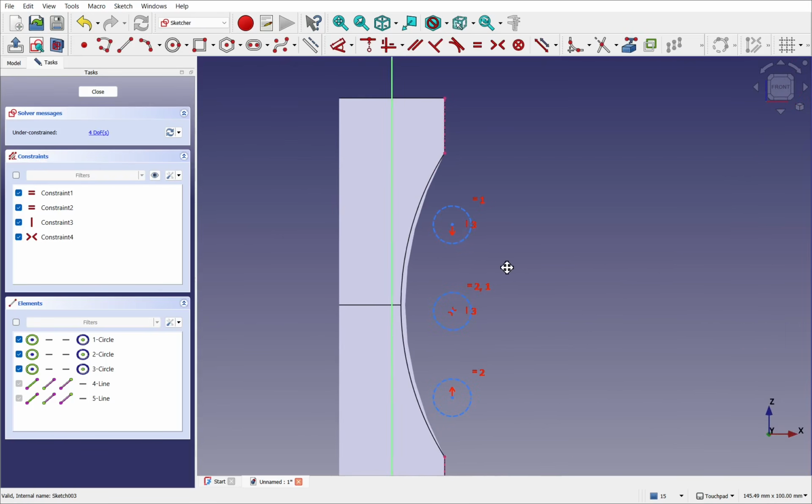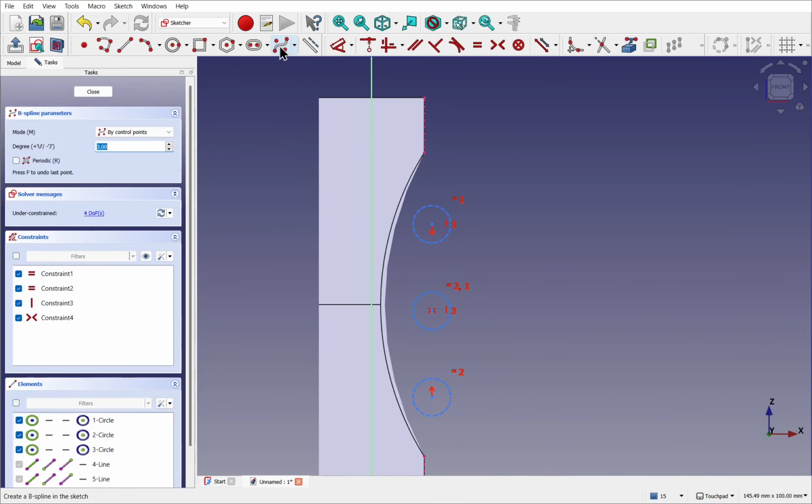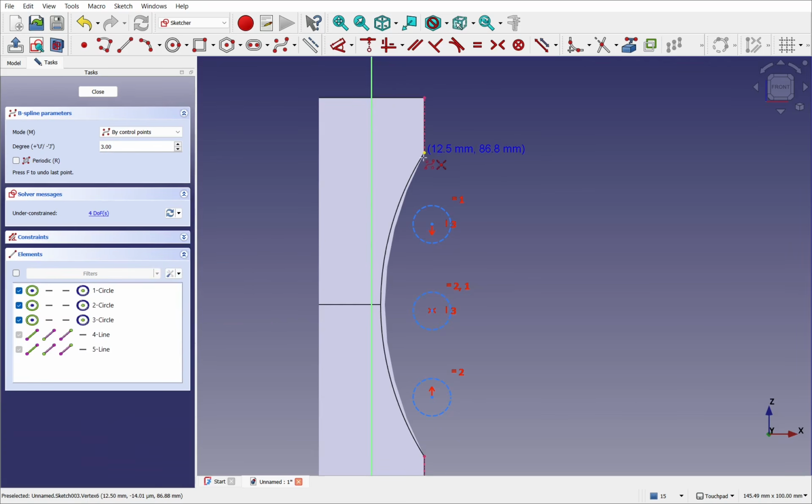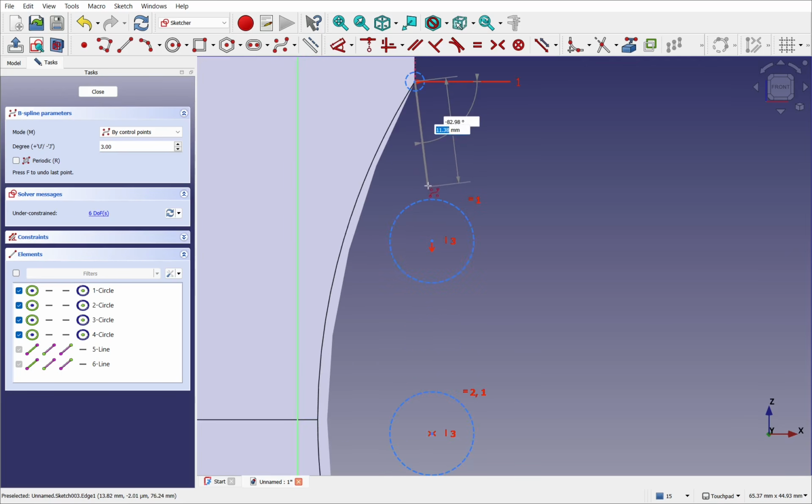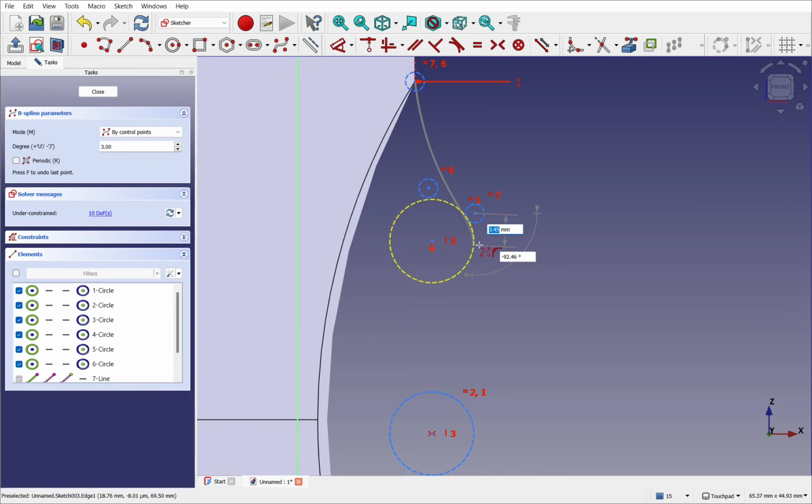Double click that sketch. Using the B-spline tool, I'm going to come in, select this point, connect up. Coincident to that, we've got the auto constraints and the auto remove redundants. So when I come in and hover over this point, constraints directly to that, and we'll come along and not connect up to the circle itself. Let's zoom in. Just going to place the point by the side of it and then come up and use the circle as a guide, making sure we don't connect to it.